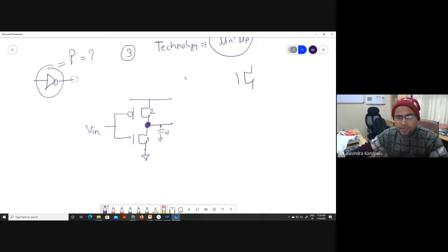I told you, basically 3C. In the RC delay model, there are three capacitances: one capacitance is here, another here, and another here in case of NMOS. If someone asks what the capacitance here is supposed to be, it is very easy: 1C because of this transistor, 2C because of this other transistor, so it happens to be 3C. Be it the charging case or the discharging case, your resistance is R. So what is the parasitic delay? 3RC, when it is not driving any load.